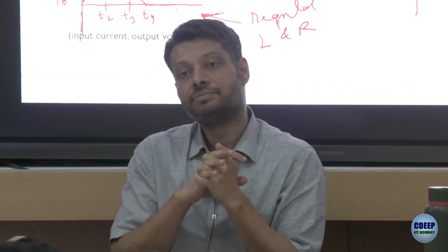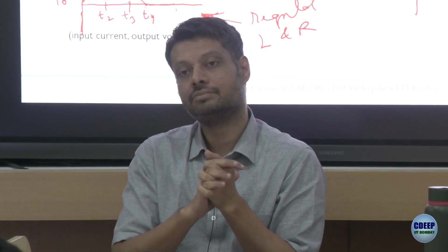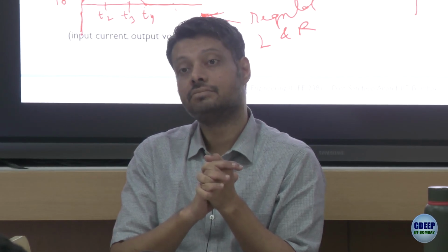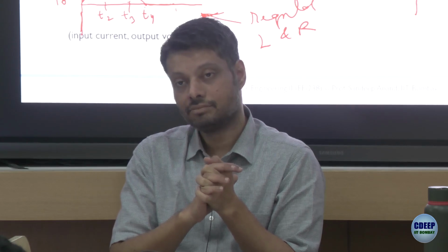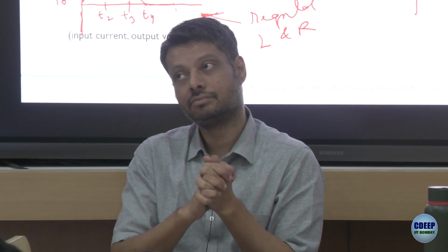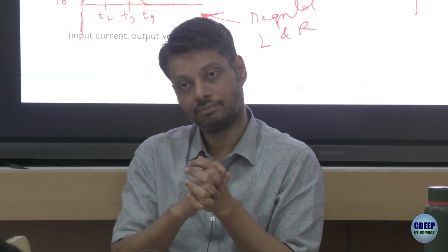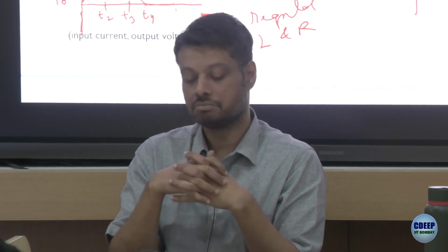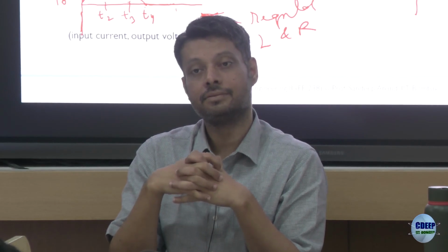Because every time here we're starting from a completely 0 point. The same frequency situation should happen in the steady state. Over a few seconds, depending on the frequency we have, it stabilizes to 50 Hertz, 60 Hertz, whatever. But here, if the diode wasn't there, I0 would have continued to go negative, but it wouldn't have become 0 again in time when V in would start its next cycle. So it would have been a proper phase shift, and over one or two cycles you would see that the frequency has become the same. But because of the diode, it's starting fresh every time.